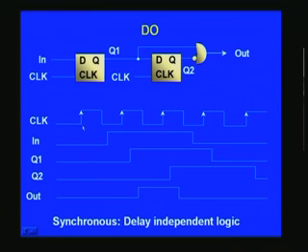The first flip flop output is Q1, and naturally when the rising edge of the clock is encountered at this point of time, in is 0. So, naturally the output is 0 here, and when it is subsequently 1 here, this will be registered only at the positive edge of the clock. That should have happened here, but owing to delay between the clock and the Q output, it is staggered a bit, delayed a bit, and otherwise it is nothing other than the input itself.